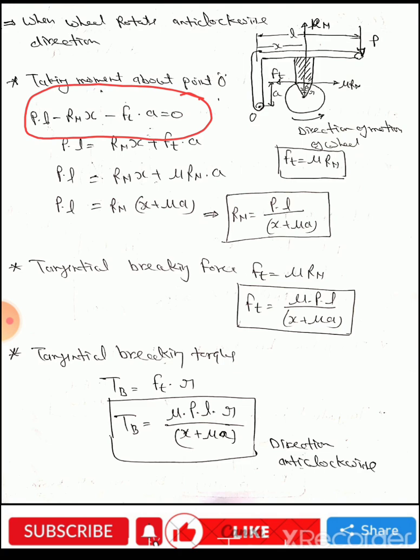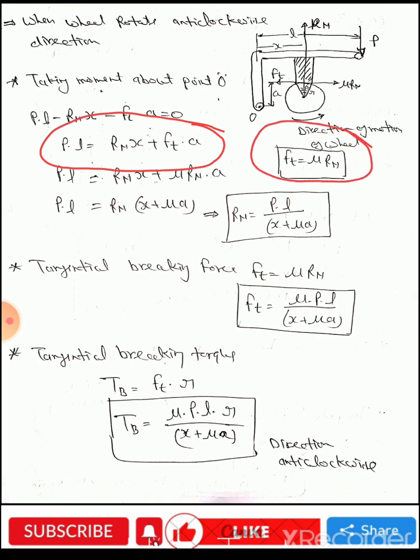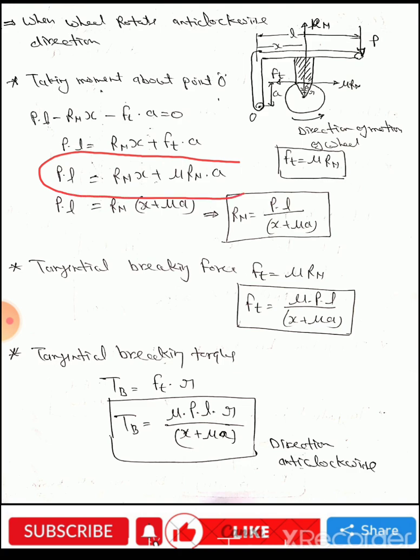We simplify as PL equal to Rn into x plus Ft into A. Putting the value of Ft as mu Rn, from here to here, we can obtain PL equal to Rn into x plus mu Rn into A. From this equation, we can take Rn common from the right hand side and obtain a new equation: PL equal to Rn (x plus mu A).